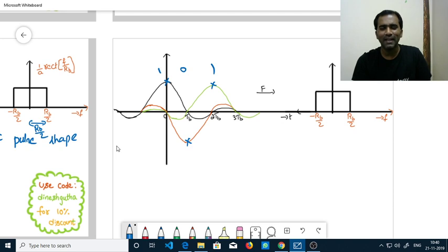But if you observe here, it looks like there is clear intersymbol interference. One symbol is definitely interfering with the next symbol because the width of the pulse is very large. Because the width of the pulse is very large in time domain, the first symbol is interfering with the second symbol, third symbol, fourth symbol, fifth symbol; it is interfering with 10, 15 symbols. Similarly, the second symbol is also interfering with 15 symbols that side and 15 symbols this side. Yes, it is interfering. But the design of the sinc pulse is in such a beautiful manner that it looks like it is interfering, but it is not interfering at the required places.